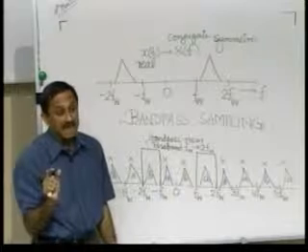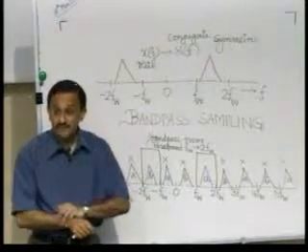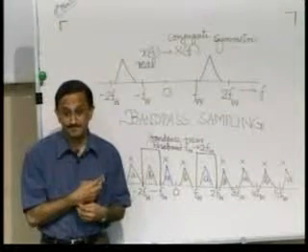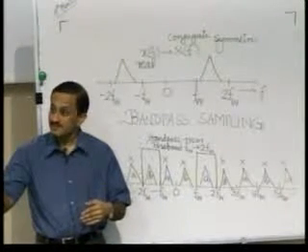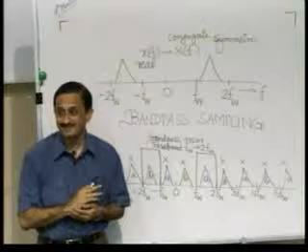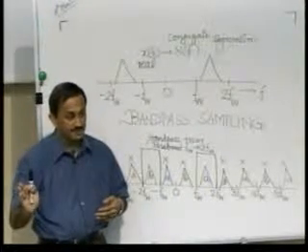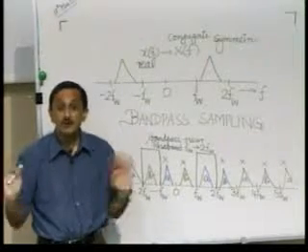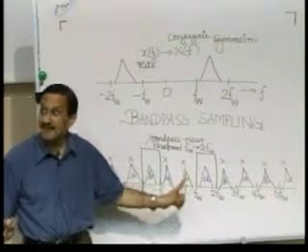Now, you see, having it more could seem to be an advantage. I mean, if you looked at the case of the Nyquist sampling theorem originally, once you go beyond the Nyquist rate, you are never at a loss. So, if your maximum frequency component is FM, no matter how large your sampling rate beyond 2FM, there is no harm done, right, whereas here there is harm done.